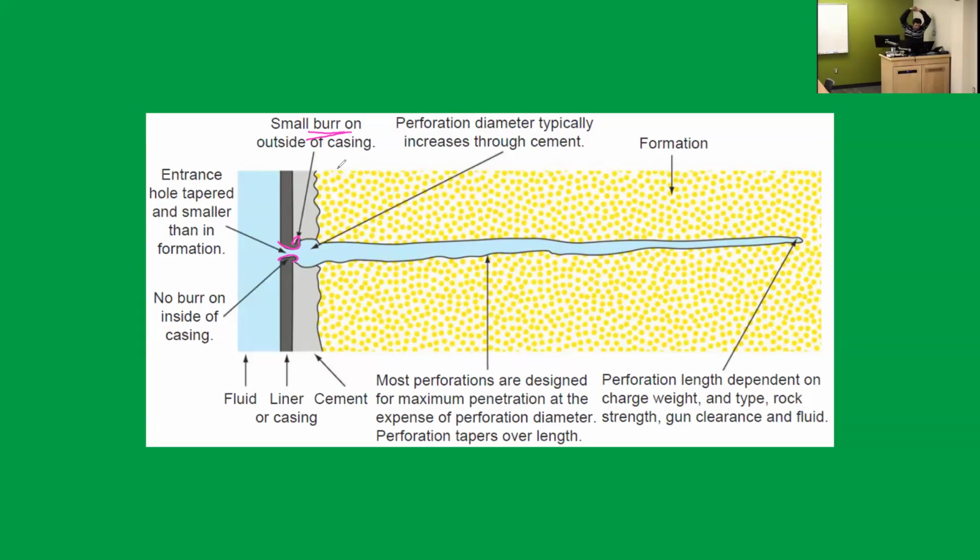Going into the formation, many times perforations are designed for maximum penetration at the expense of perforation diameter. Then you care more about length than diameter, sorry, but it can be vice versa. In fact, I care more about what happens at the perforation base than what goes on at the tip. As a mostly hydraulic fracture guy, that's what I care about, because the fractures won't start at the tip. They will start at or very close to the base.